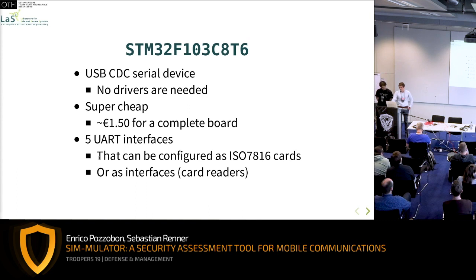The microcontroller is good because we don't need to code any drivers on our own, since the STM works out of the box as a USB CDC serial device. It is super cheap. We had it just lying around in the lab, and it has UART interfaces that can be configured to work basically as pins and as ISO 7816 cards or interfaces.